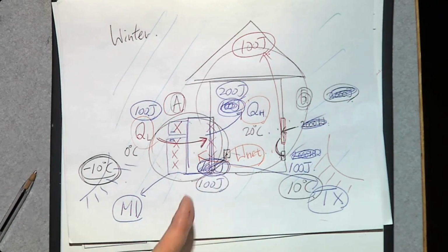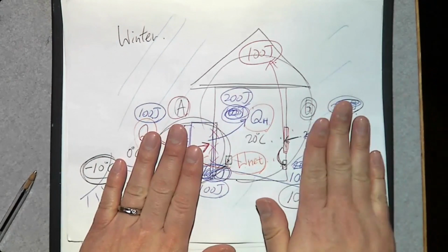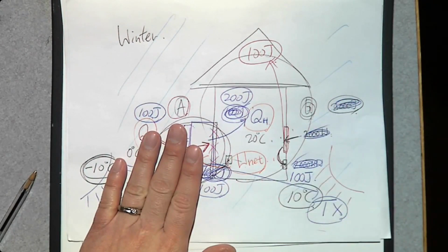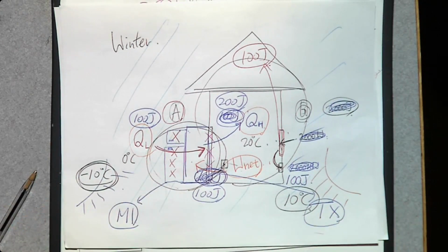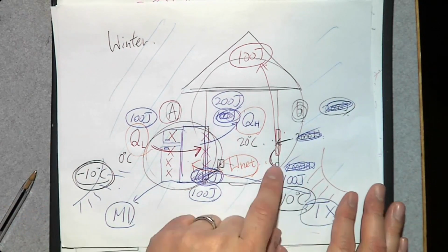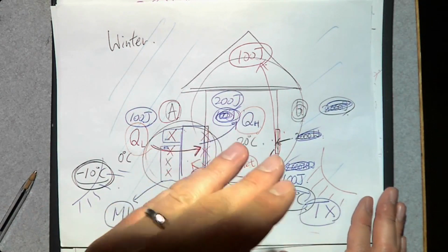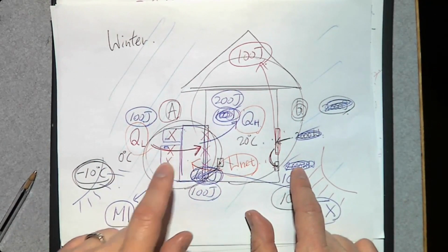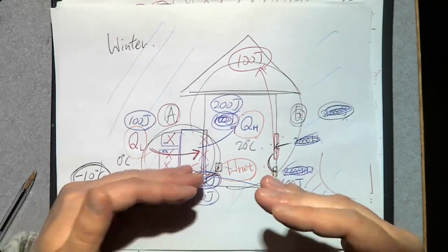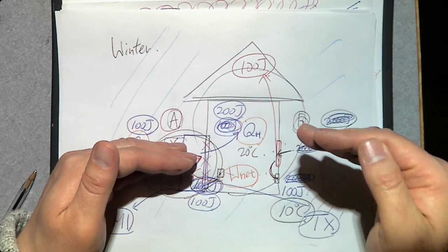because the heat pump is more efficient. However, there's a fundamental problem in this analysis because I'm comparing a heat pump and an electric heater. What is the heater in your house, if I may ask? Is it an electric heater or a gas heater? An electric heater is more expensive than a gas heater because gas price is much lower. So if you compare a heat pump and an electric heater, the heat pump is more efficient because we are talking about the same price electricity. However, gas price is usually lower than electricity.